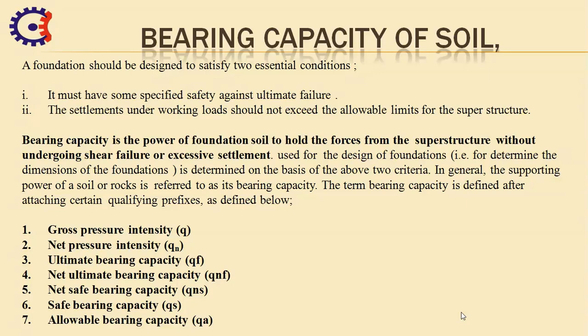As we know, the bearing capacity of soil is the most important part before constructing any structure. A foundation should be designed to satisfy two essential conditions. It must have some specified safety against ultimate failure, and the second one is that the settlement under working load should not exceed the allowable limits of the superstructure. Bearing capacity is the power of a foundation soil to hold the forces from the superstructure without undergoing shear failure or excessive settlement.